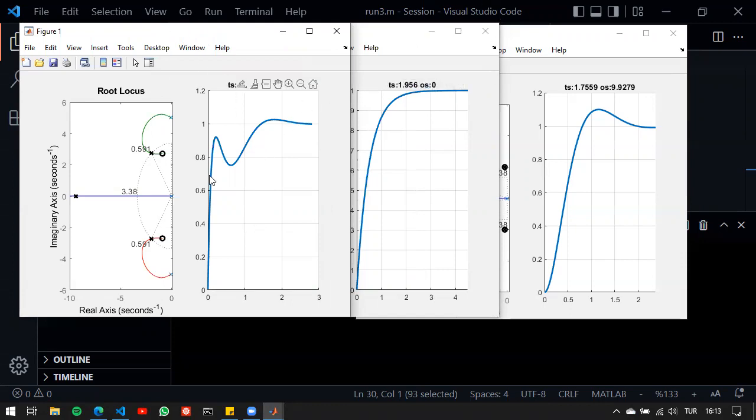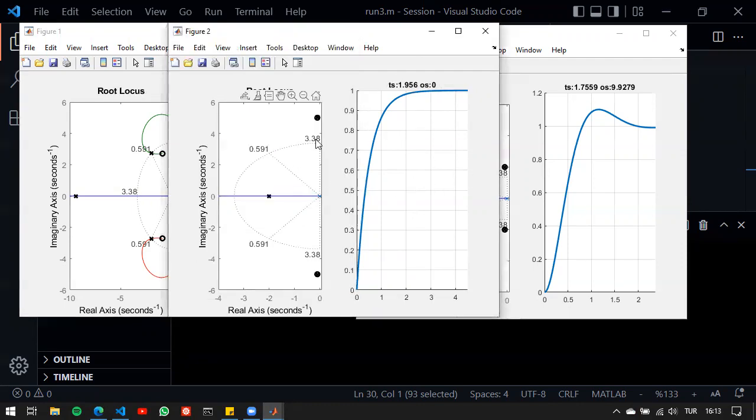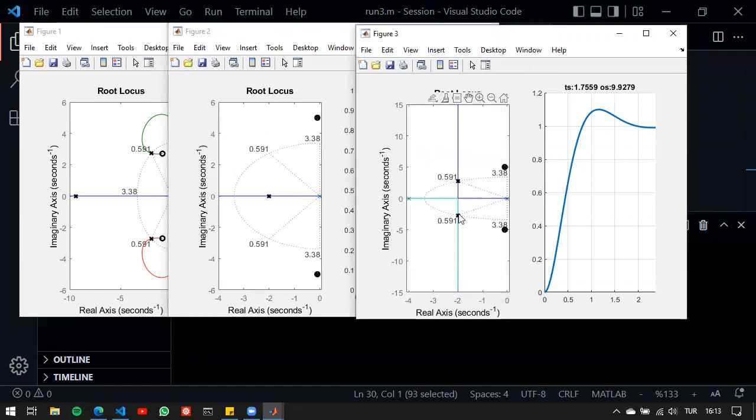Maybe 0 overshoot is good for such a system and controller combination, because we are on the real axis if we get rid of the poles. That's a good one. Or we have to update our controller, which we did in this case. So we added another pole. It is sort of a pre-filter type times PID controller. And this gives us the overshoot that we were looking for.